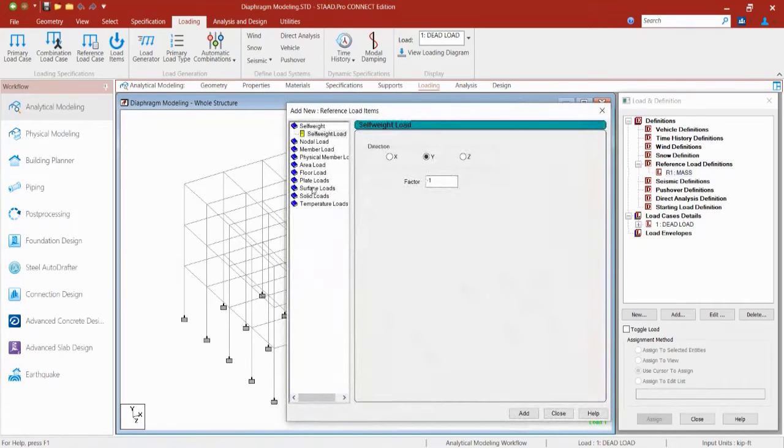And then from this area, I can see all of the different options I have available for modeling that mass. Now in STAAD.Pro, all masses that are capable of moving should be modeled as loads applied in all possible directions of movement. Even if the loading is known to be only in one direction, there's usually mass motion in other directions at some or all of the joints in your particular model.